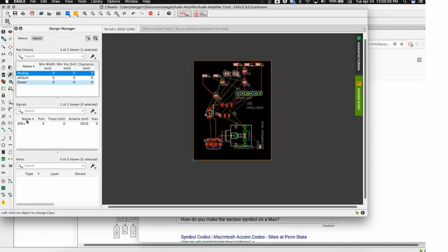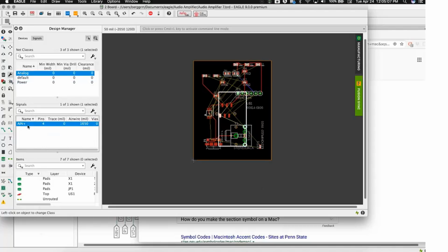One of the big moves for us going forward is going to be to bind design rules more tightly with net classes and try to create a really strong relationship between classes of objects. Not just net classes, but classes of objects of some particular type, and the rules that then get applied to those things. It makes it much easier to selectively add objects to a group and associate a rule to that group than to assign rules to each individual object. So as we move forward, expect that net classes will take on much more of a role as a first-class citizen. I think they're underplayed within the existing Eagle, and I don't think it's fully appreciated how powerful they can be.